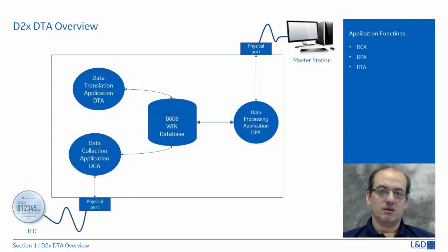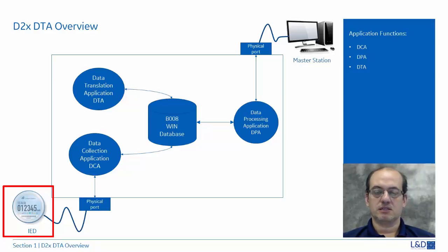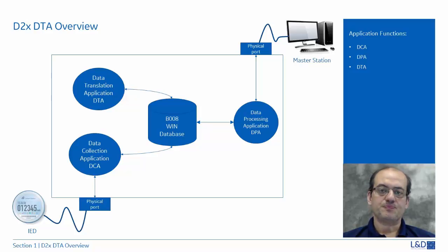The information would be created in the field as digital information from a sensor or a meter that's measuring something, or a relay that's taking certain important action, or from a peripheral like an I/O card that is connected to these sensors or inputs from the field. Once the information is available in the field, it's then formatted in a protocol and transmitted to the physical port that it is connected to. That physical port could be either a serial port or a network port.